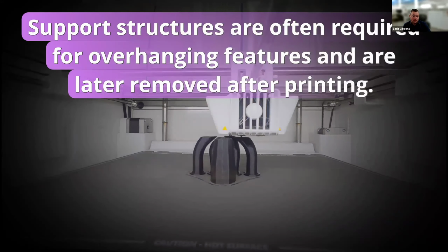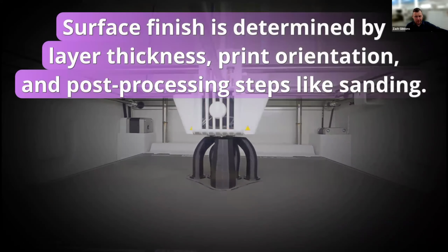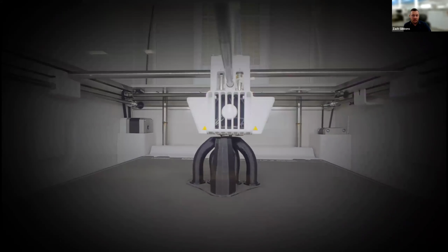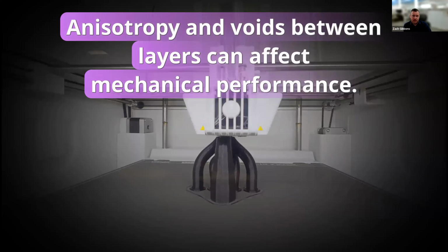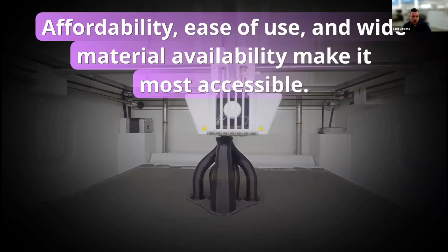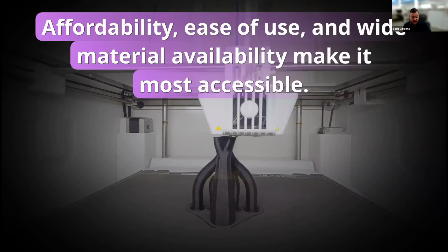Support structure is also something we possibly need to be worried about in 3D printing. We generally cannot print in open space. We need a substrate to be able to build on top of, right? So we add these layers together and we stack them to get our solid part. Anisotropy and voids in these layers can cause defects or quality issues. We're going to briefly touch on that.